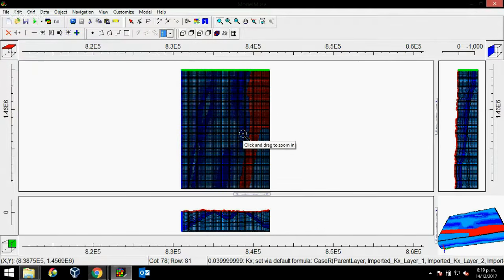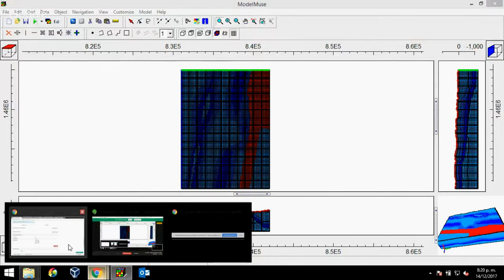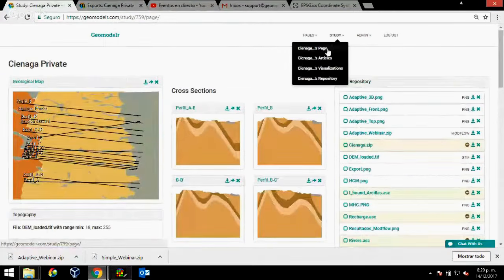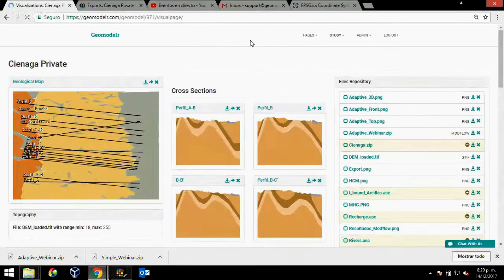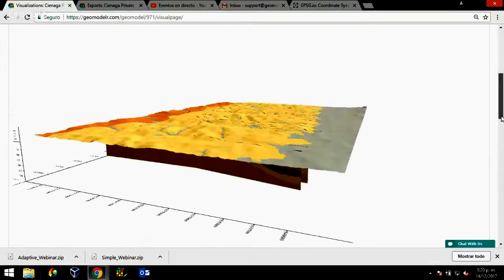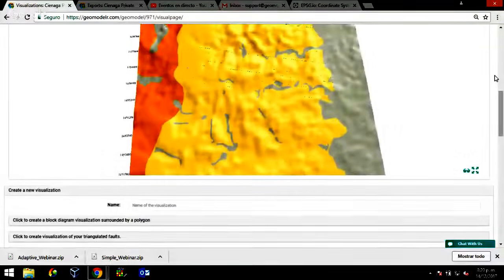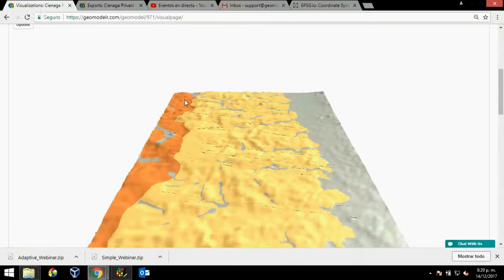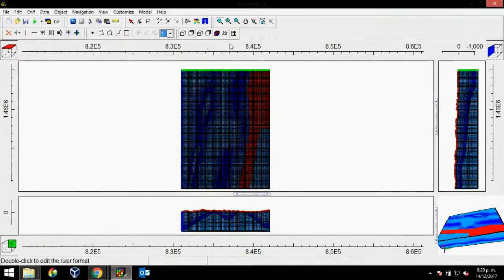Then from this point, we're going to make an example of a simulation using river condition and recharge condition. Firstly, if you remember, Ricardo said that we don't create a unit that corresponds to clays. This unit that we are now using in our model corresponds to clays, and we are going to inactivate this region using an ASCII raster file. Let me show you how. Select file.